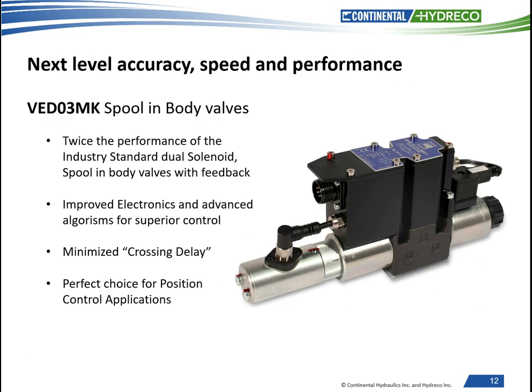The next two product groups that we will be reviewing are used in applications that require higher levels of performance and control. When the application requires high-speed moves and precise control over position or force, the valve reaction time and the ability to accurately follow slight command signal changes becomes very critical. Although the J series valves are very good and rated up to about 45 Hz operation, they may not be good enough. Generally, any manufacturer's valve similar to our J series will be very close in the overall performance specifications.